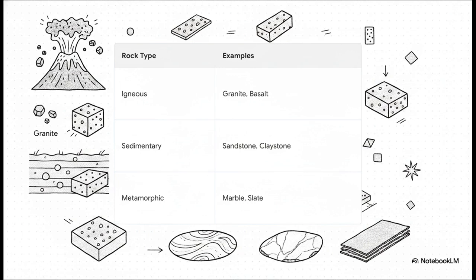And the base minerals, whether we're talking silica, silicates, carbonates, or sulfate, totally dictate the properties of the aggregate. Oh, and fun fact, this is also why engineers categorize sand by its source, like pit sand, river sand, or sea sand. The origin drastically changes its chemical makeup and even the sharpness of the grains.